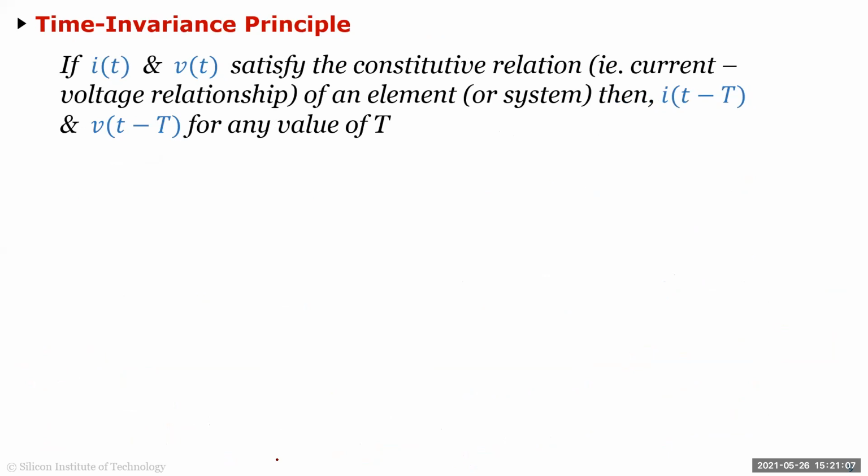So you tell me what is this equation then? Yeah, I don't know what ferroelectric does. So is this still valid? Yes, sir. Then it is linear. Okay. But actually for the ferroelectric, this is not valid because this is a function of V. If this is a function of V, then you'll see that if you apply superposition, it isn't valid. So that's why it's nonlinear.